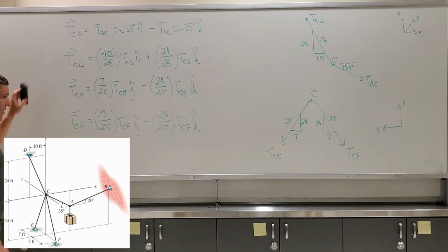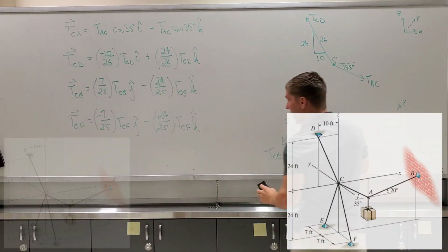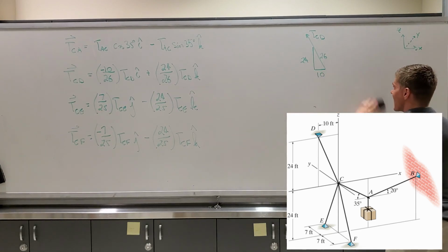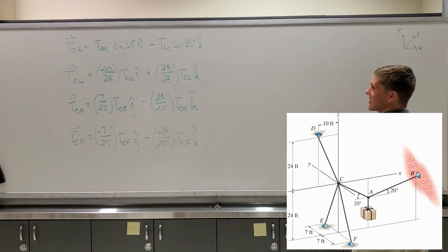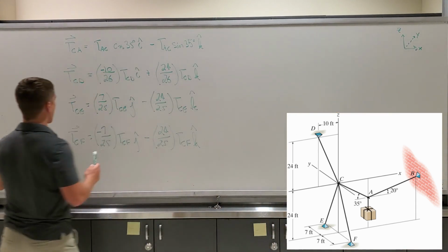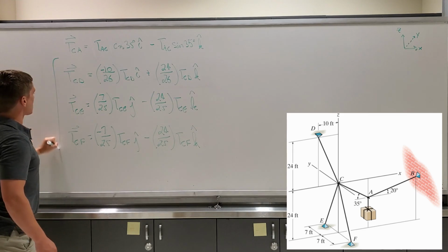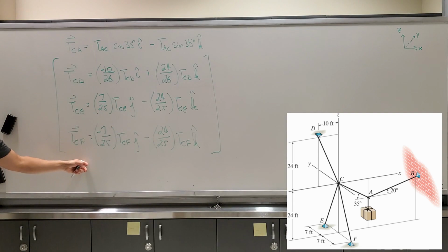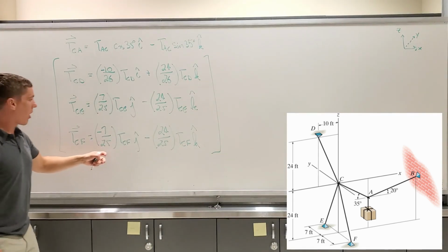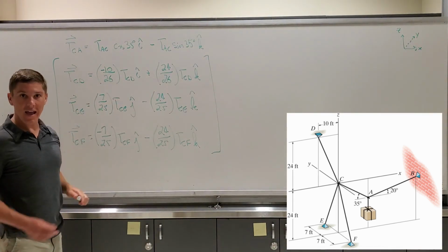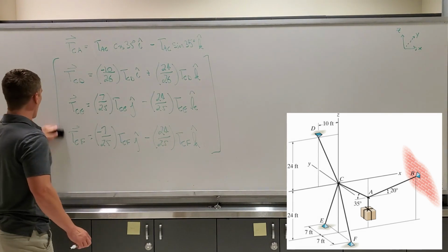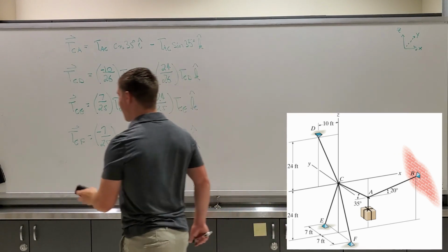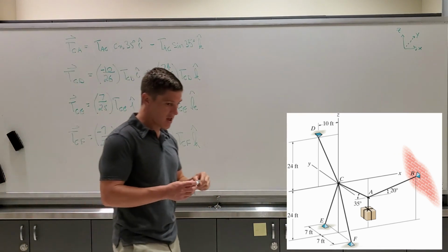But now, the other big mistake that I see students do all the time is they think that once they get to this point they can just solve this system of equations the way it is. You may have these three equations for particle equilibrium, and you put that directly into the matrix on your calculator and try to solve it. That is not the case. Recall that you need to have your i's and your j's and your k's all separated into your force equations. So our next major step is that we need to break this into our three equilibrium equations.